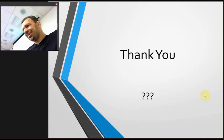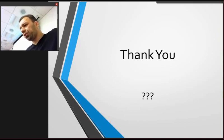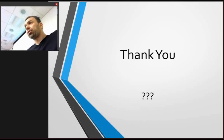Hi, I do have a question. Sure. So if you excite through a hammer, do you need to know how much force you're exciting with? Okay, so the question was if you need to know the force that you are exciting with. The answer is no, because you have the force sensor that will measure this for you. Good, thank you.